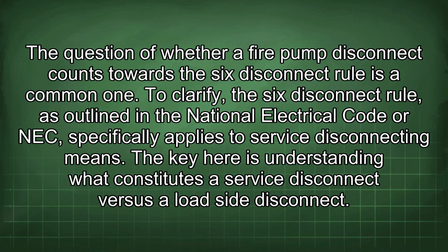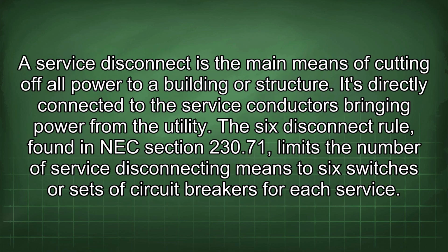The question of whether a fire pump disconnect counts towards the 6 disconnect rule is a common one. To clarify, the 6 disconnect rule, as outlined in the National Electrical Code or NEC, specifically applies to service disconnecting means. The key here is understanding what constitutes a service disconnect versus a load side disconnect. A service disconnect is the main means of cutting off all power to a building or structure.